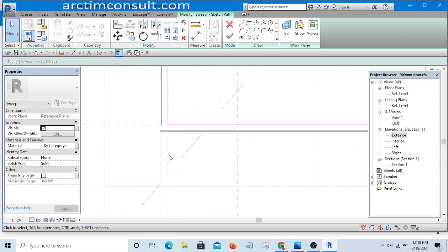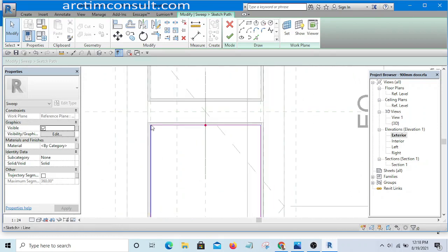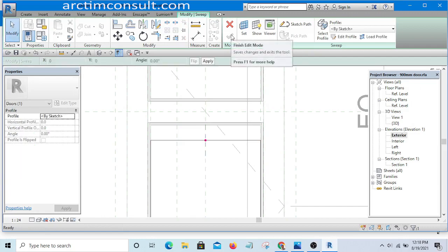Here I have a reference plane. I can align it to here. I can align it to here. Then I don't have a reference plane here that can guide me, and I don't want to lock it to a model part. But I can use dimension to lock it. Okay, let me fix the reference plane there so that it will be my guide.